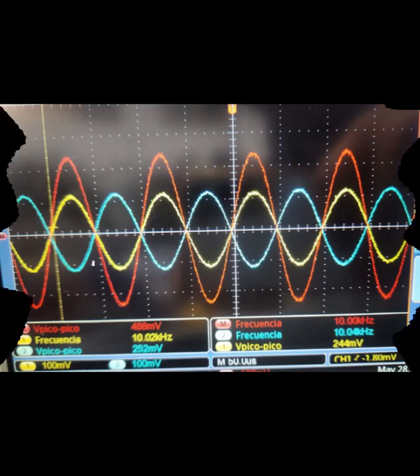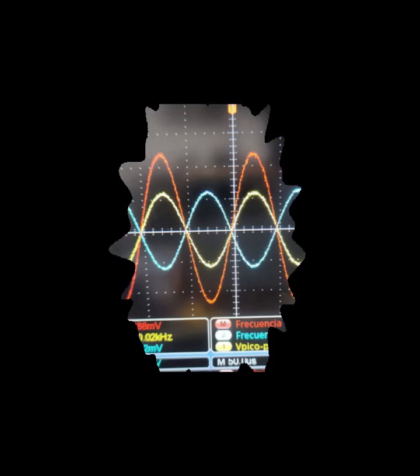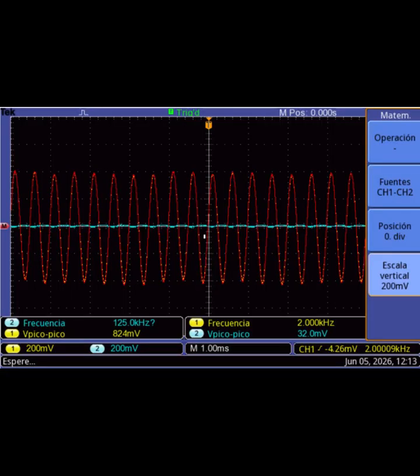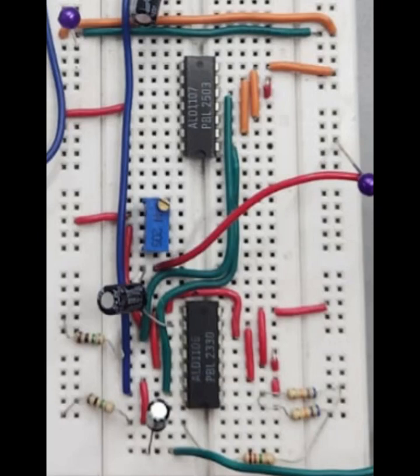To improve the amplifier performance, the drain resistors were replaced with MOSFET active loads, as shown below. Unlike passive resistors, active loads provide a much higher equivalent resistance, increasing the voltage gain without requiring larger resistor values or a higher supply voltage. The experimental implementation and oscilloscope results are in the pictures.